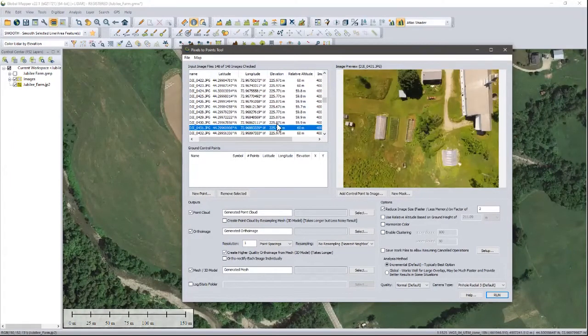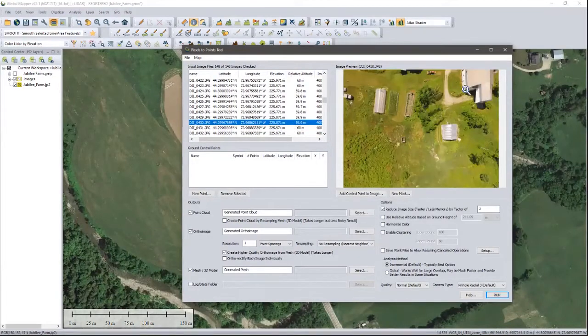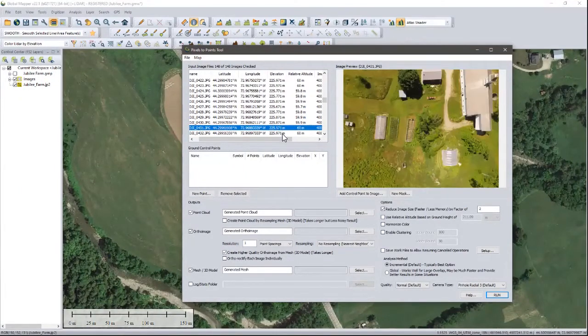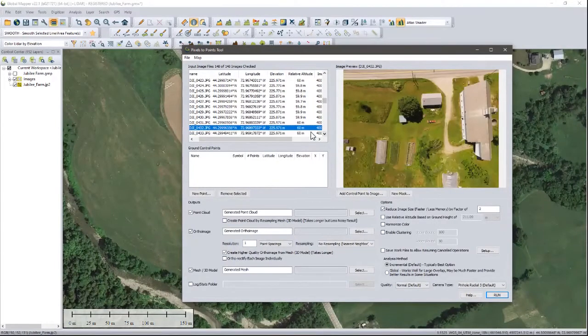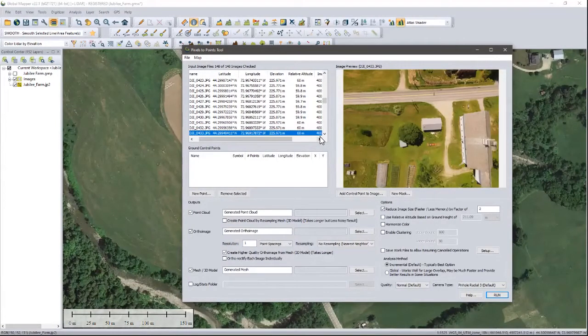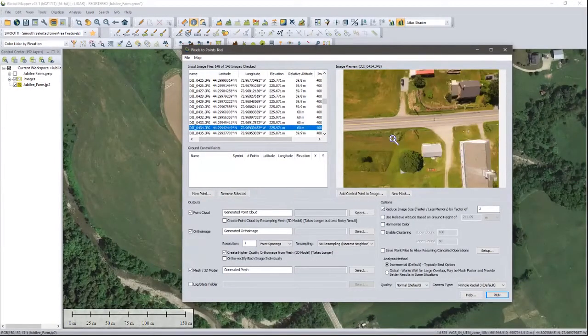Now, noting what happens with the adjacent images, I'm looking specifically at this farm building. Hopefully, you're seeing this on my screen, right over here on the left side. As I transition through each subsequent image, you will notice that my perspective of that building changes slightly. I'm looking at it again from a slightly offset vantage point. Now I'm starting to see the wall on the far side of my building, which I wasn't seeing before. And this again illustrates the inherent process we're going to be applying here, where we're looking at a set of pixels basically in that image from multiple perspectives.